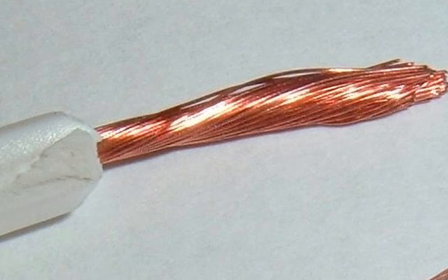Remember, current going through a wire, not voltage, but current going through a wire creates heat. And if we have that wire in a hot place, it won't be able to take as much heat before it gets so hot that it could be a danger, because the insulation that goes around a conductor is only made to get so hot.